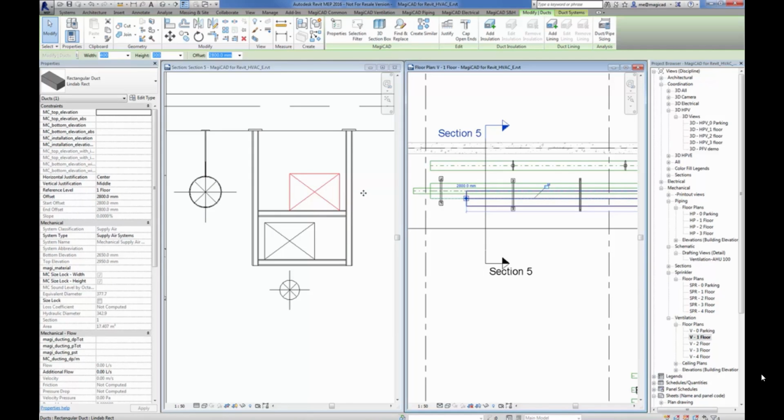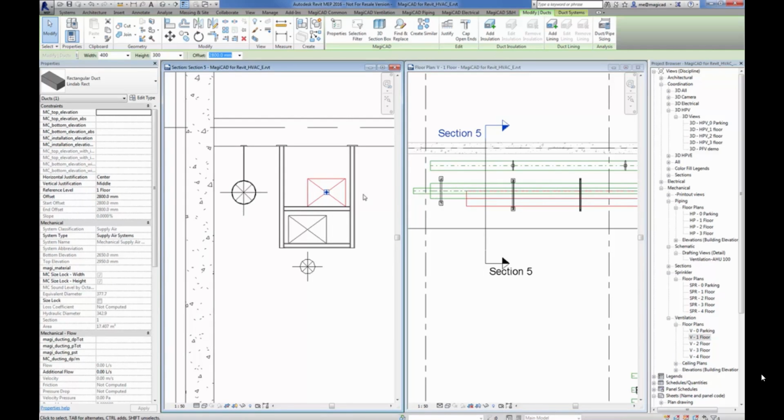So this is what I meant during the presentation when we have this numbering. Auto size: the duct is changed, the hanger type is recalculated. Auto follow: if something moves, the hanger type adapts to it. If the host is changed or moved, or there's another host appearing, then there are special functions to be used.